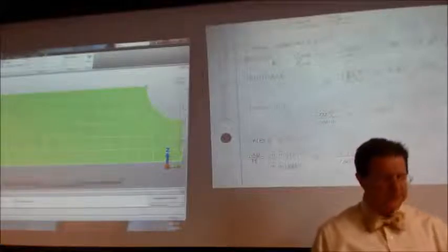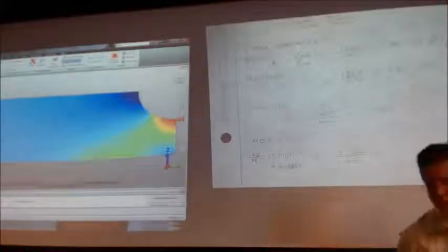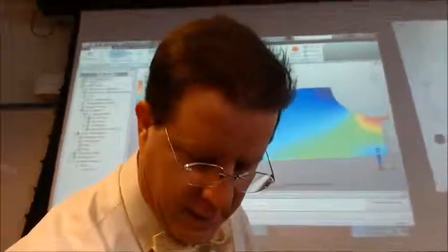Then the last thing, if we go to symmetry, because we're wanting to prove that symmetry works, for this one, the max value here for deflection was within 10% of the same mesh size that we had for the full model at this particular juncture.